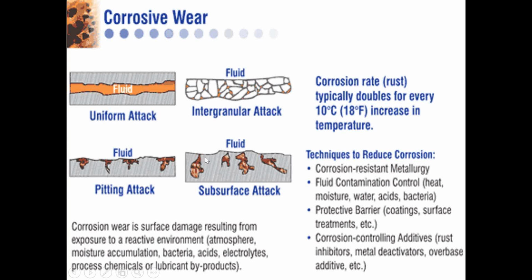And then another thing that happens, what if we get moisture down at the bottom of that pit? What if our oil oxidizes and we get a high acid number? So now we have some corrosion going on. We have some temperature changes going on. We have all the pressure of the bearings running across this surface. And eventually, we destroy that bearing surface in the micron stage, but eventually the damage becomes big enough that the human eye can see.